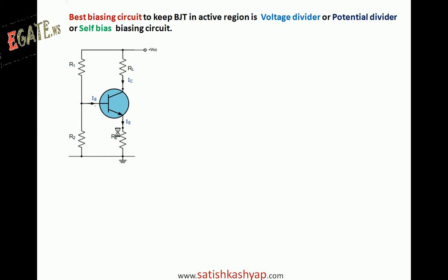And since you are applying constant voltage and resistor values which you are not changing, that is they are also constant, what we expect is constant currents flowing in the transistor. Those constant currents are called DC currents or quiescent currents, and because of that there will be a constant voltage across the transistor terminals. They are called DC voltage or quiescent voltages.